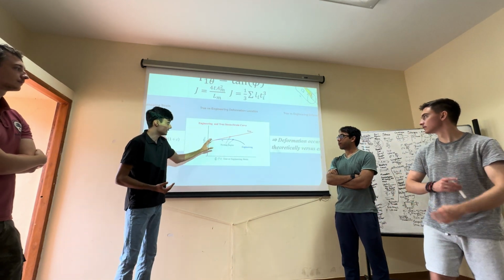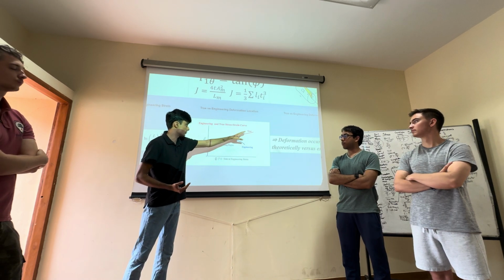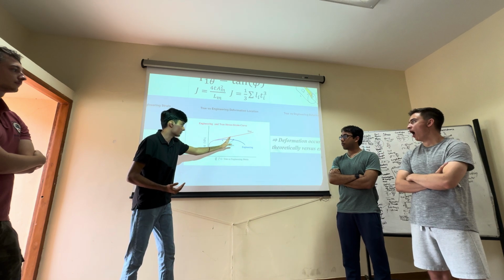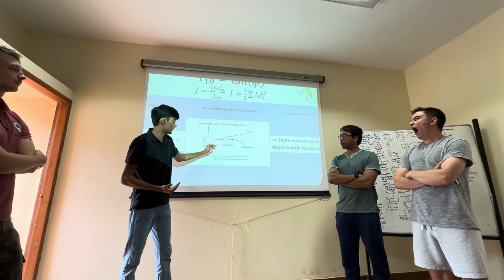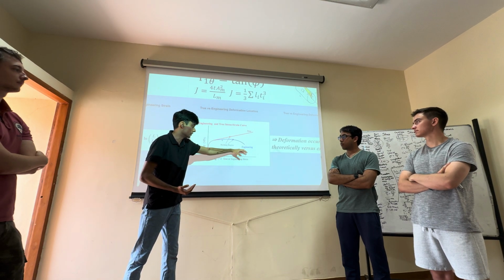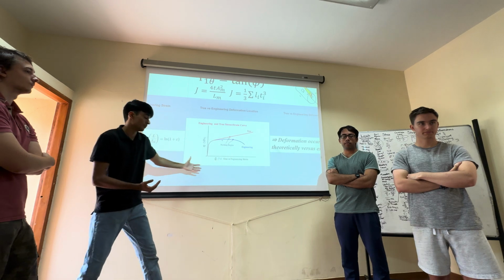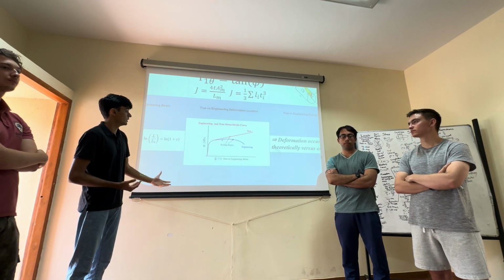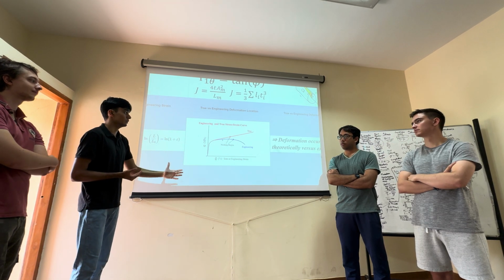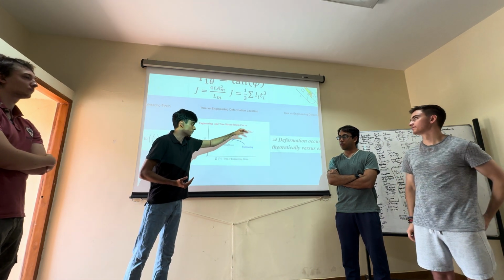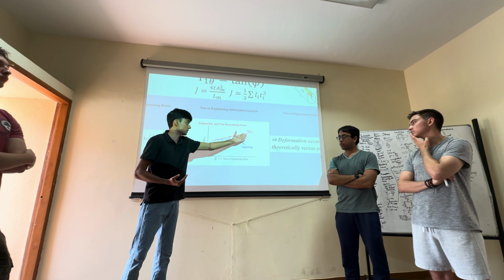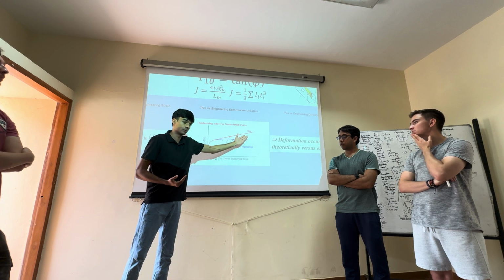Now we can see that theoretically, with the true stress and strain curve here, it just keeps going, right? Obviously, necking occurs at different points here because of that. And then, when we're looking at graphs, we're usually looking at the engineering or experimental version of what's going on, because that's more useful to us. But based on equations and theory, it would be a completely different curve, and the curve would end at a different location and have a different relationship. Here it shows more of a linear relationship, right?